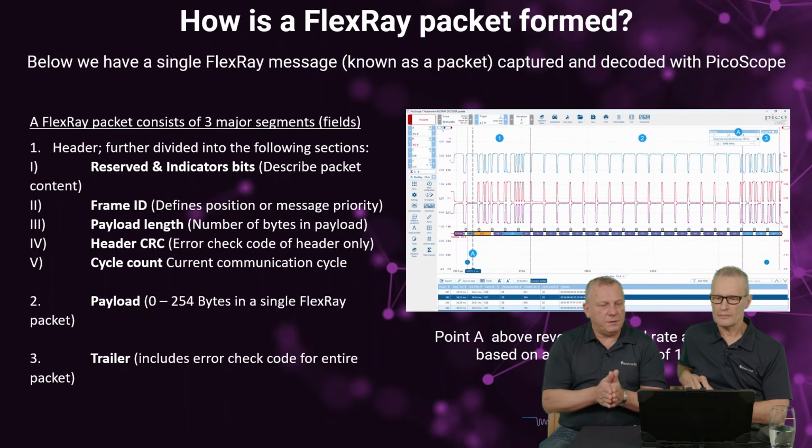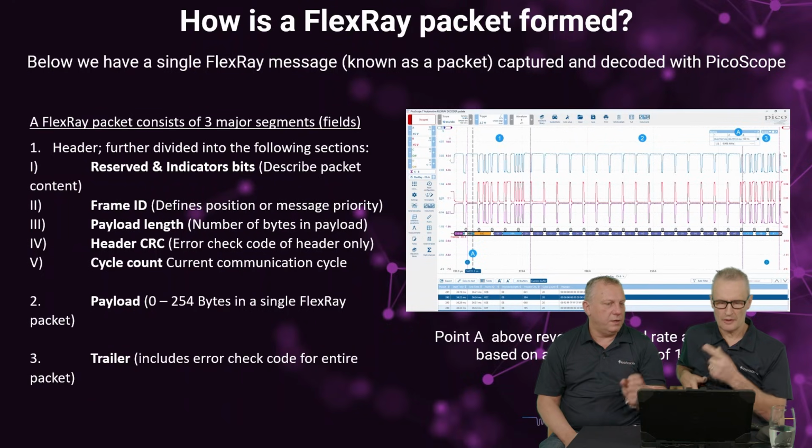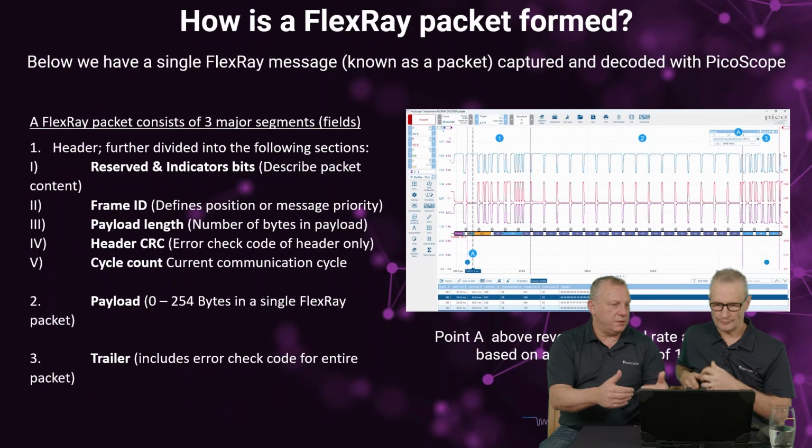And there are obviously error messages that we can use, but once again, as you identified, the frame ID is important, because we can start to identify what is or isn't on a network. Or, as you said before, we can remove something from the network and see which ID disappears, and then we can start diagnostically to see what's going on by taking a measurement and using the decoder.